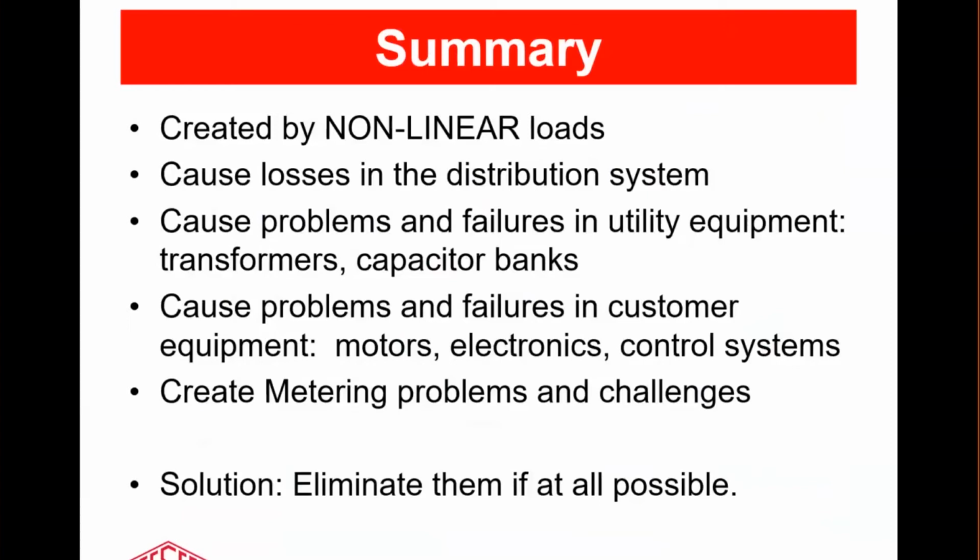So we're seeing different meters, and this was much more prevalent 10 years ago before we started working on this in the standards bodies, but we still have most of the meters that are deployed, which under harmonic conditions don't give the same answer for VA or power factor.